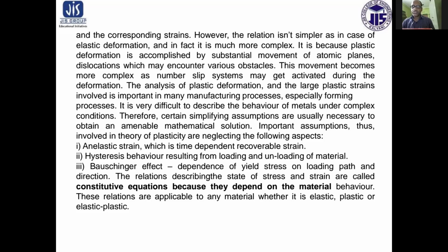In fact, it is much more complex. It is because plastic deformation is accompanied by substantial movement of atomic planes and dislocations, which can encounter various obstacles. This movement becomes more complex as a number of slip systems may get activated during the deformation. The analysis of plastic deformation and the large plastic strains involved is important in many manufacturing processes, especially forming processes.